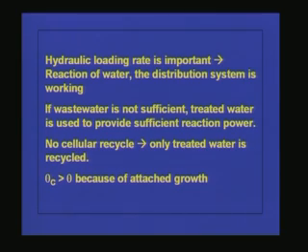So, in trickling filter we have seen the organic loading rate as well as the hydraulic loading rate. But coming to the hydraulic loading rate, in trickling filter the hydraulic loading rate is very important, because I have already discussed how the distribution of wastewater is taking place in the trickling filter. It is because of the hydrostatic pressure available in the distributing arm. So, if enough hydraulic loading rate is not practiced, what will happen? The hydrostatic pressure available will not be sufficient for the movement of the rotating arm. So, in such cases we have to supply power externally.